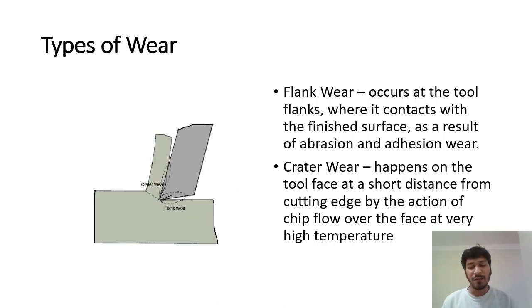Okay, so tool wear measurements have got mostly to do with capturing a very good image of the face that you want to measure, and we use microscopes for that, of course. And once you have a very good image ready, it's all about just using visual tools in the software to get the flank wear value. So I'm not really going to go in depth about what flank wear and crater wear are. I'm sure you have done quite a lot of study on it in your lectures and in your coursework.